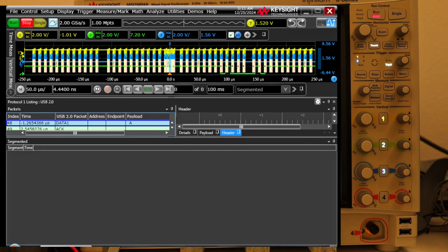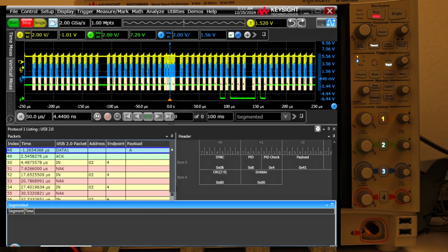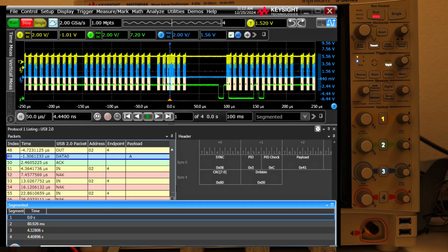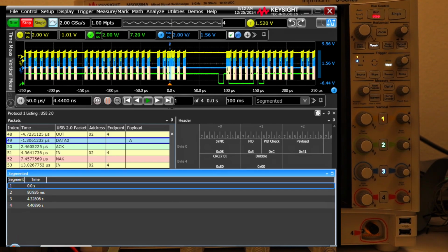Let's go down in this view, and let's see if we can also look at the segment itself. Okay, so we will do a single capture. I will press the same button A, and I have pressed it. Okay, so we got some segments, and now our oscilloscope's advanced segmented memory shows you how far that packet was. So you see, we captured 4 segments.